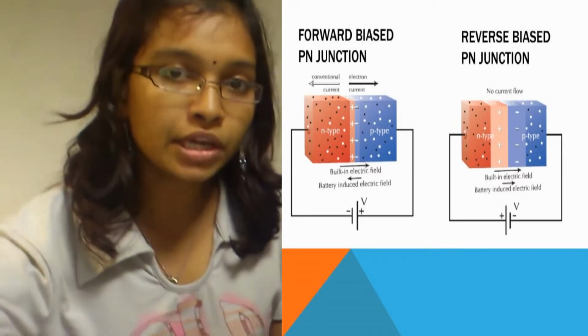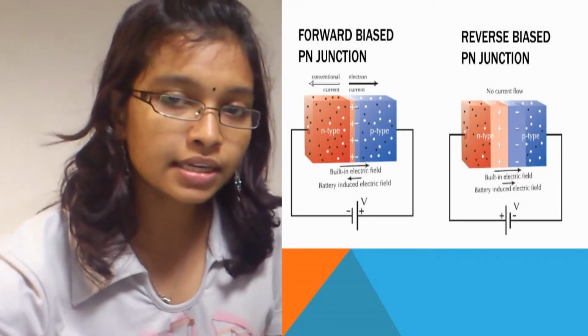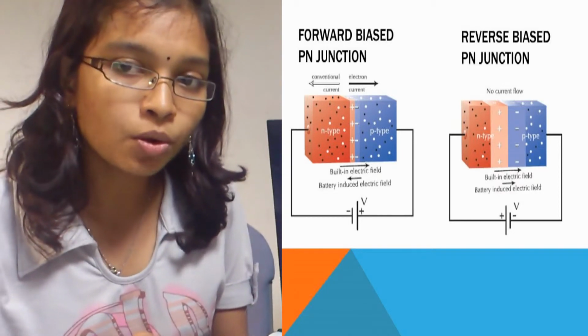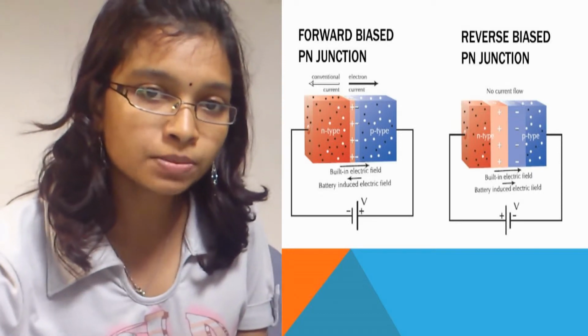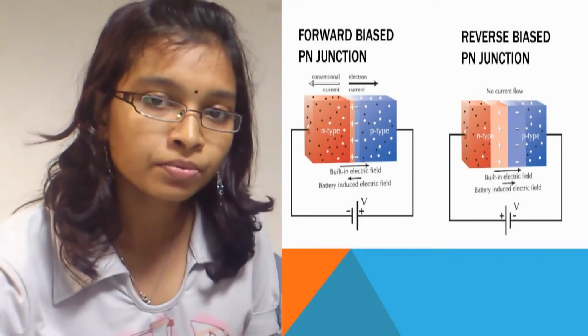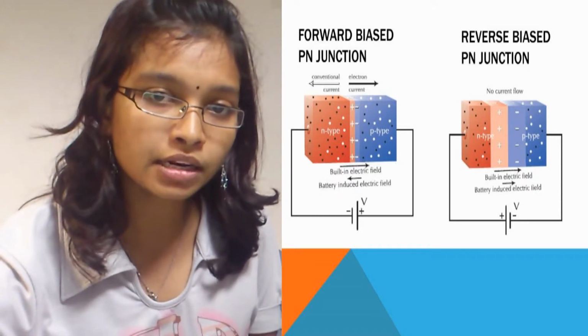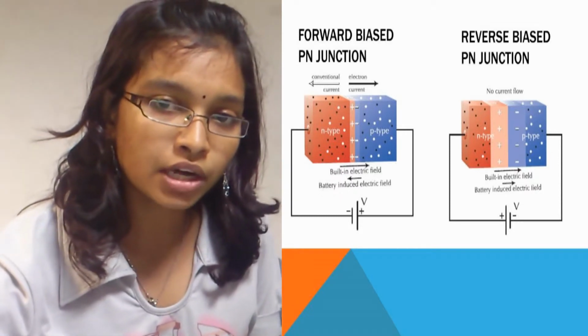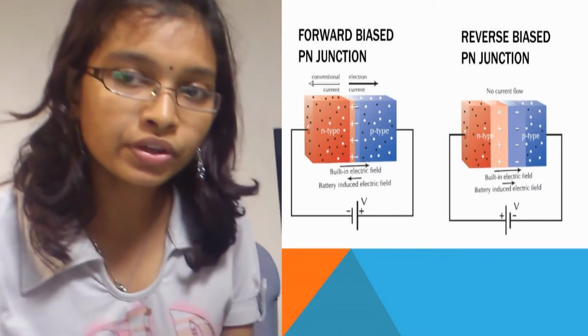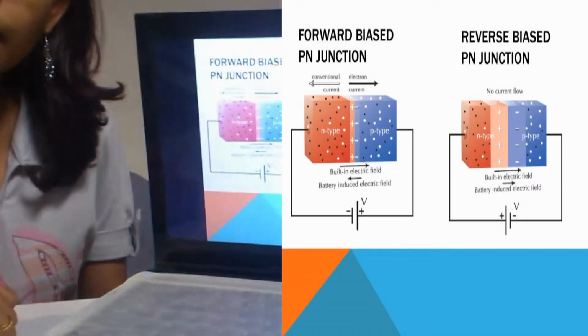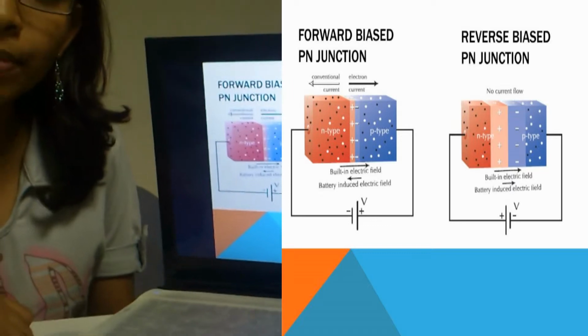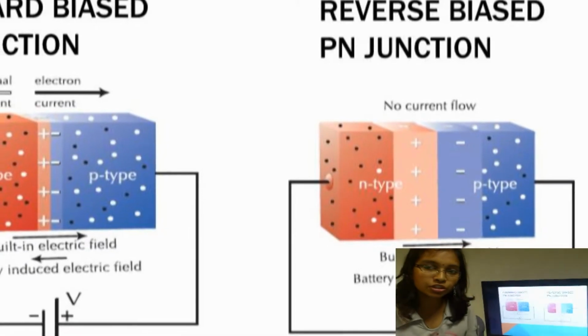An applied voltage in the forward direction, as indicated, assists electrons in overcoming the Coulomb barrier of the space charge in the depletion region. At the depletion region, the built-in electric field and the applied electric field point in different directions. When these two fields add, the resultant field at the depletion region is smaller than the magnitude of the original built-in electric field.